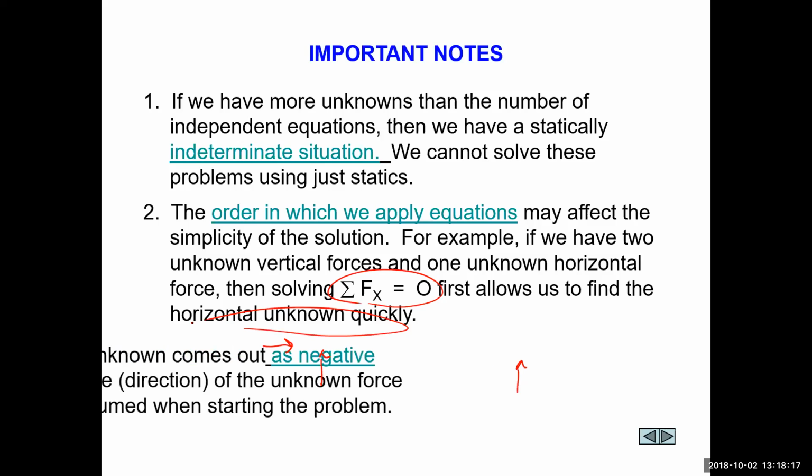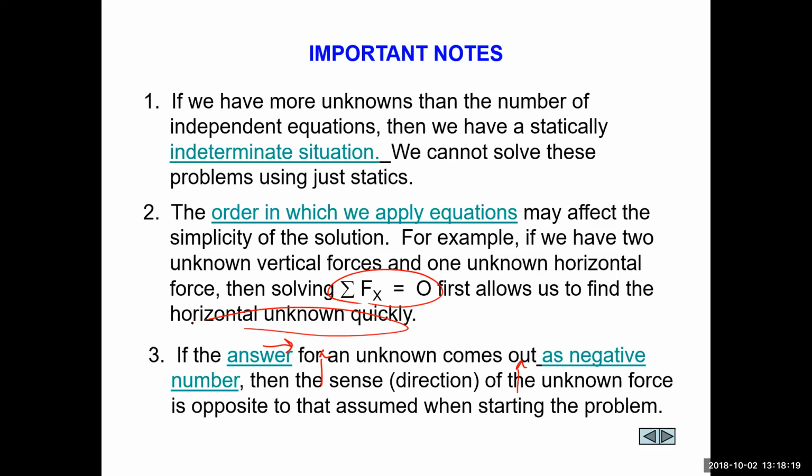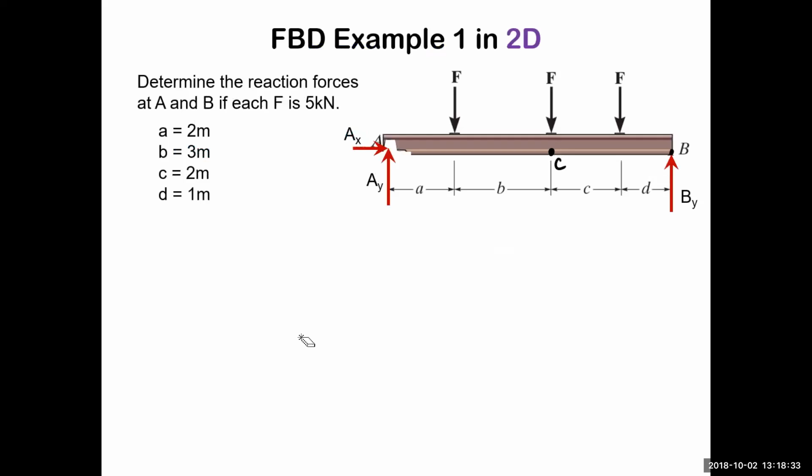And as you'll find, if the answer for an unknown comes out as a negative number, that means the sense of the unknown force is opposite to that assumed in starting the problem. And we'll talk about that and what that actually means in a second.